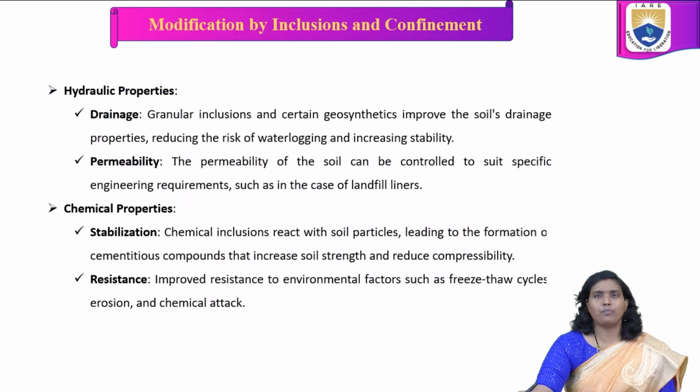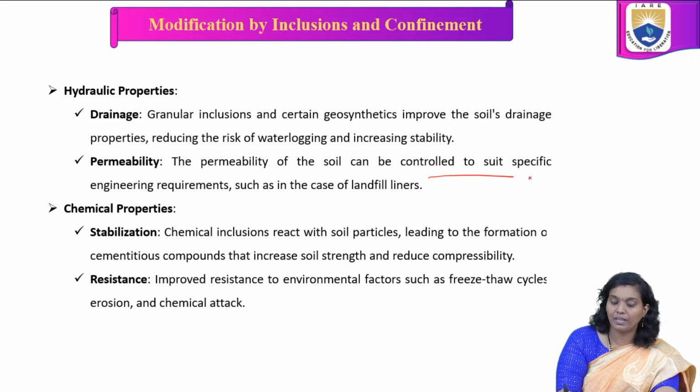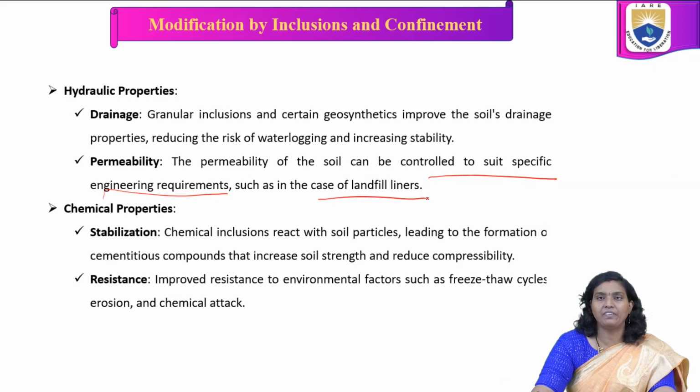constructions. In hydraulic properties, granular inclusions and certain geosynthetics improve the soil's drainage properties, reducing the risk of waterlogging and increasing stability. In hydraulic properties, we are also considering permeability. The permeability of the soil can be controlled to suit specific engineering requirements, such as in the case of landfill liners.